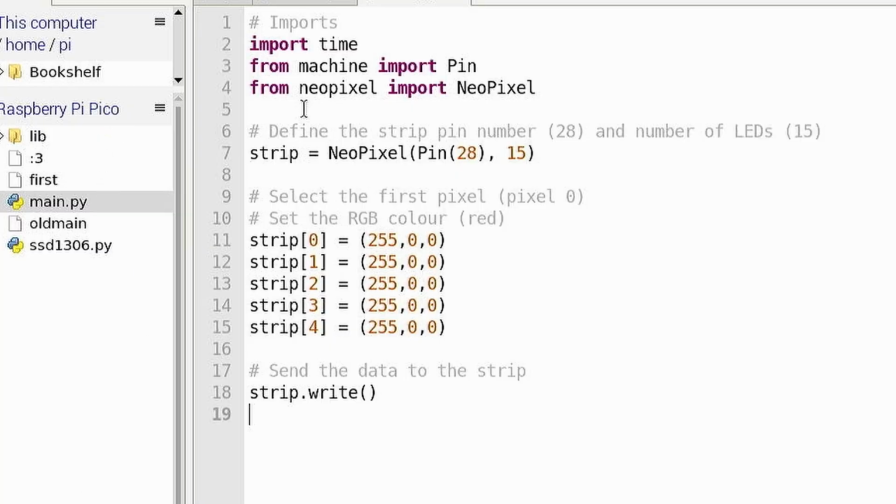So basically what I've done is I'm going to put this code in main.py, so it should run on auto boot. And then I'm going to move the power to something that has more potential amperage available, because maybe there's something with the Pi 400 supplying it, just as an experiment, or we'll try a different cable. But this should turn on every time and light up all 5 red, if it's okay. And this way I can rule out a power thing, okay? So let's push this code to it. All right, so that should run on boot. So let's see if it does that after.